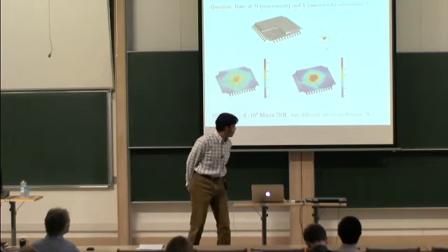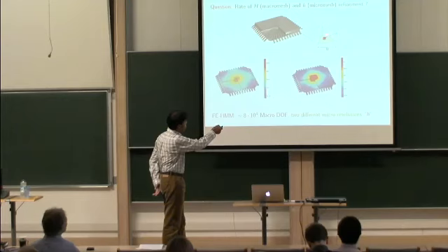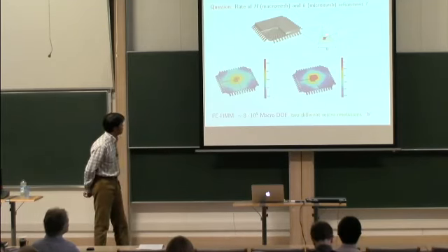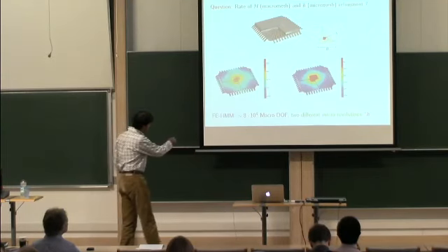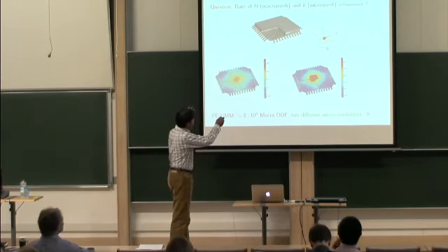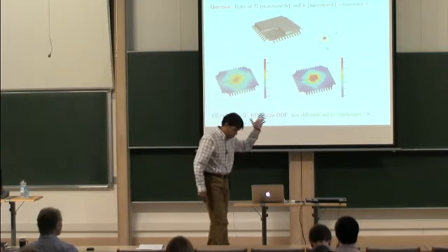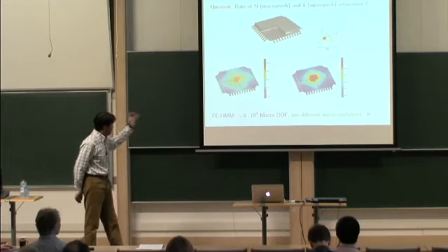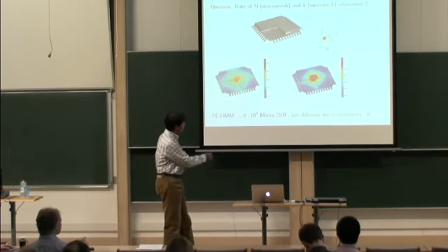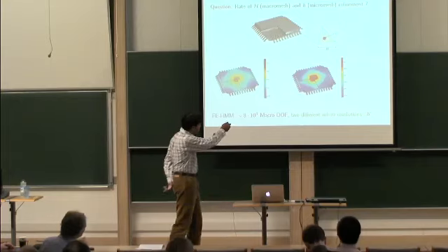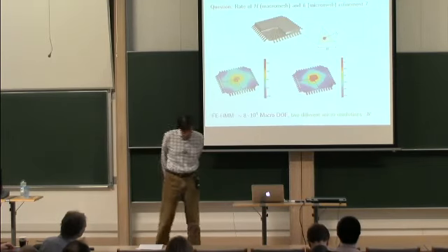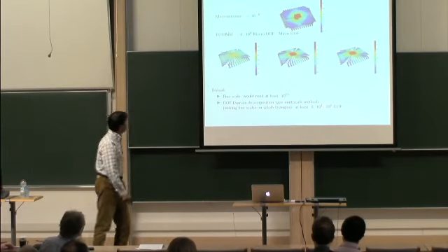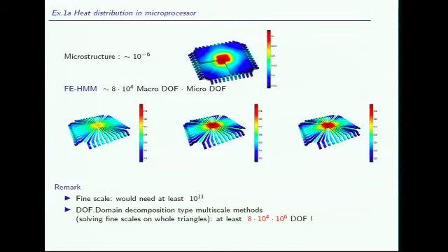So the a priori error estimate that we have tells us that we have to refine the microscopic mesh, and indeed, if you do that, you have a better accuracy of your simulation, okay? So if instead of doing that, we would have made the choice to refine the macroscopic mesh, we would end up with a much, much more expensive problem, okay? Many millions of tetrahedra, and in each tetrahedra sampling domains, while in fact, we do not need to do that. We just only need to refine the microscopic mesh, which is also costly, of course, but that's the most efficient way to proceed. Okay.